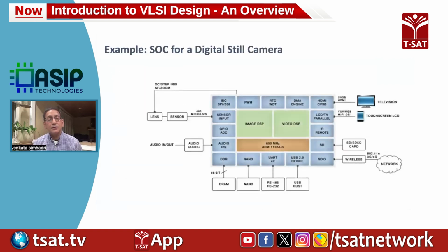Here is an example of an SoC block diagram, how it looks like. This was an SoC that was used in a still camera. You can see that it has an ARM CPU and then an image processing DSP, video processing DSP, and multiple interfaces to talk to various things, for example, an image sensor, interfacing to a TV or a touch screen, and also talking to a wireless connection to transfer your data in and out.